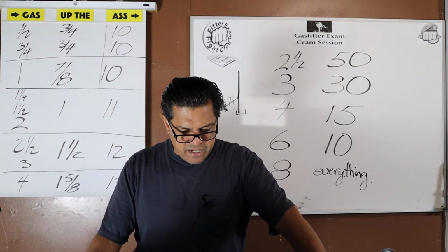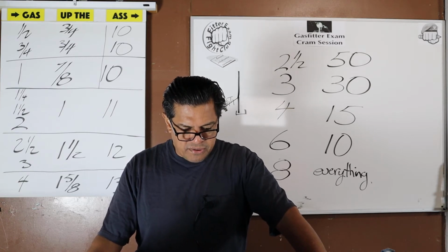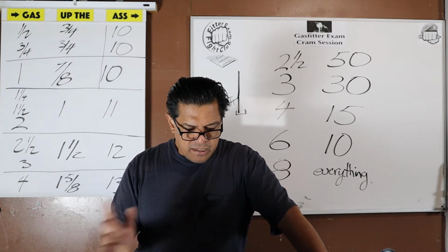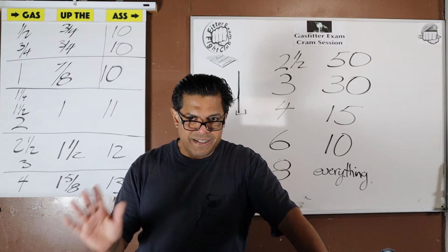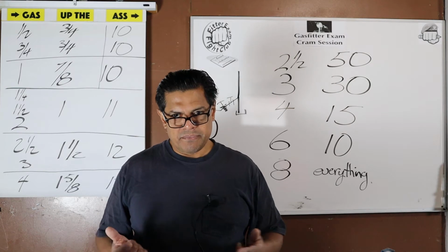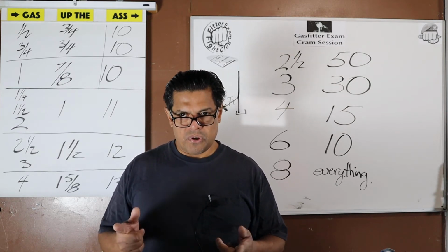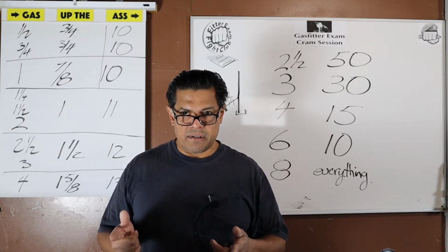It's all steel now, but wrought iron remains in the text of the code. You'll probably never see it, but it's an acceptable material. For the sake of review, let's go over the other ones to see what is not acceptable material. Cast iron pipe, too brittle. Copper or brass pipe, too soft. Aluminum pipe, even softer than that, no good.